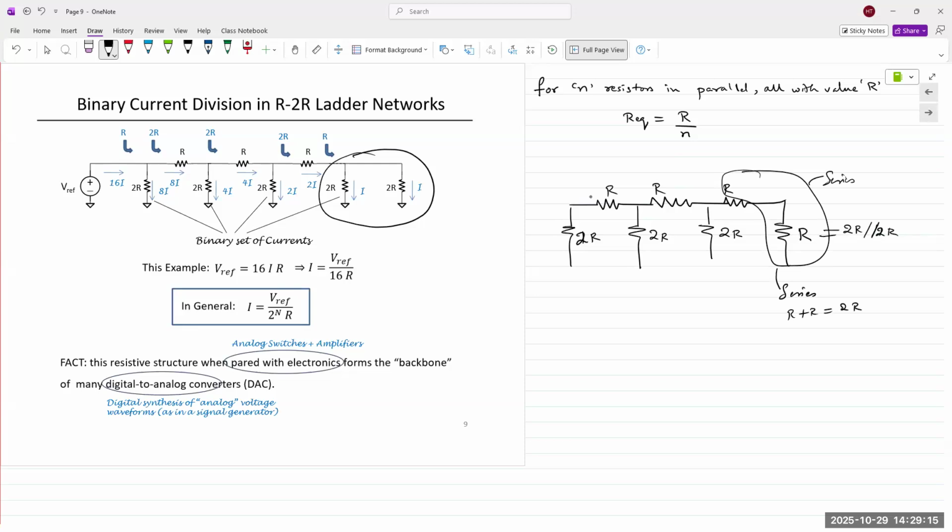So going forward, this 2R and R is R, along with this in series gives me 2R, is then in parallel with 2R, again gives me R, R plus R, 2R, 2R and 2R in parallel, and again finally R plus 2R, so 2R and 2R in parallel. And that's how you reduce the circuit, starting from the very right, moving towards the left.